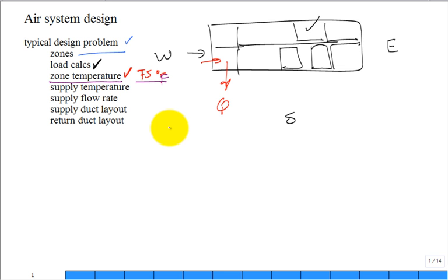I'm thinking of summer, and I'm thinking of air conditioning. And so what is the temperature of the supply? You can't dump in negative 10 degree F air. That's just not feasible. So what are they going to dump in? Basically 55 degree F air. Oh, you can wiggle that around a little bit, but the numbers just come around and around that you're going to dump in 55 degree F air. So now it tells you how much heat you can remove based on the flow rate.